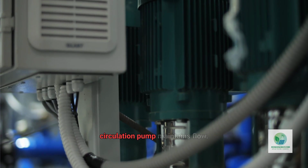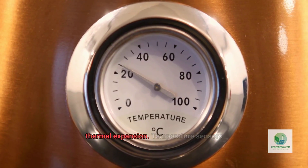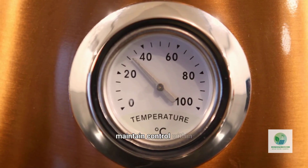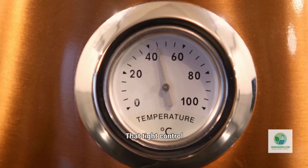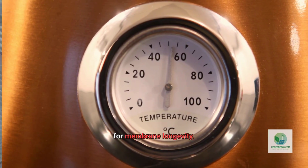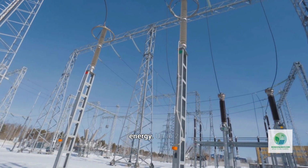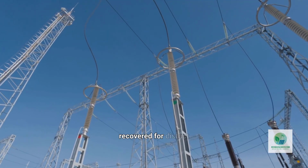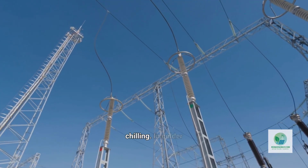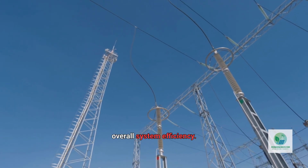A circulation pump maintains flow. An expansion vessel accommodates thermal expansion. Temperature sensors maintain control within plus or minus 2 degrees Celsius. That tight control band is critical for membrane longevity. Optionally, waste heat recovery can extract usable thermal energy. Up to 2 megawatts from a 10 megawatt module may be recovered for district heating or absorption chilling. In colder climates, this improves overall system efficiency.